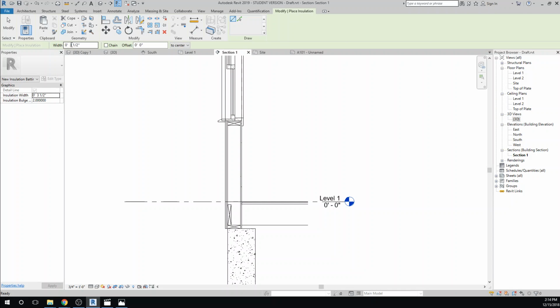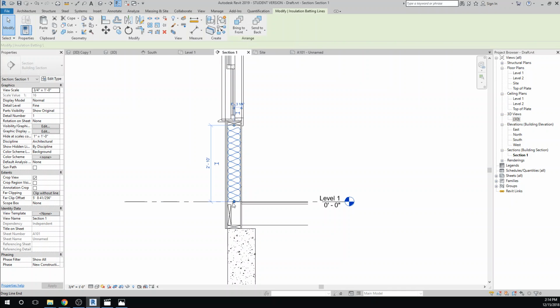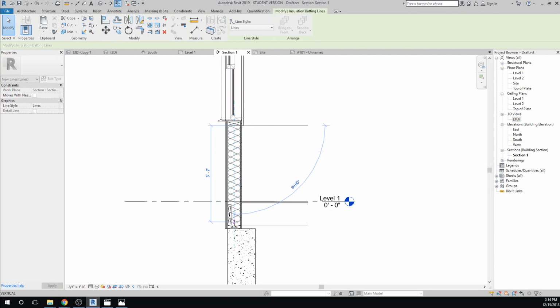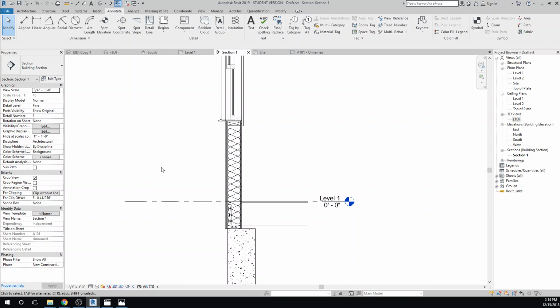In this case, we're going to put it in the wall joist, so this is the symbol for insulation, so I'm going to make it 5.5 inches. And we won't get a good, well, I guess we will. There's the center of that stud, and I'll just pull that up, and you'll see how we've drawn some insulation. And we'll pull this down. And so we've started now detailing the insulation that goes in the wall.